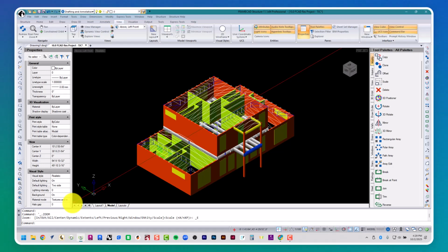Once I finalize the upper roof trusses, I now have enough information in terms of gravity load as to what the walls on the second floor need to look like, because there's a definitive design for the trusses above them. We'll see every single stick, top plate, bottom plate of each of those trusses. And once we design that, we can move on to designing and building the second story walls,